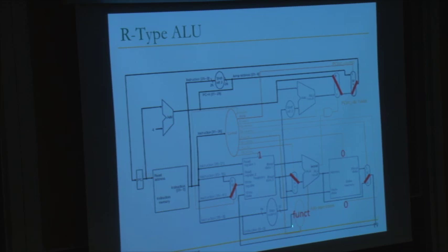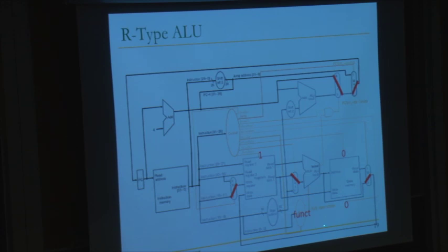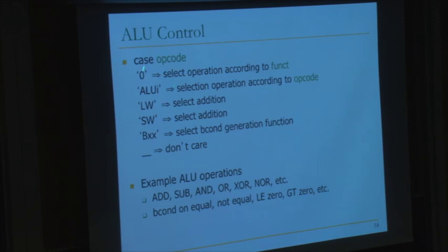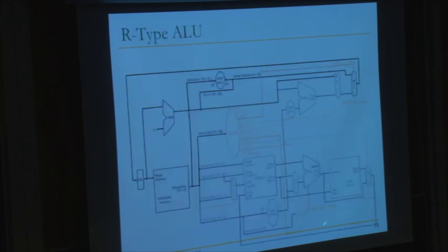And there should be some logic here that actually determines what the ALU should do, right? You're going to implement this logic. So control actually is not only this block, but also this block, right? Which includes the branch condition logic too. So if this is not a branch, you're going to select this function based on the opcode. That's actually, it's not only a branch, but based on this, you'll implement this logic. Okay? Well, you're not reading from memory or writing to memory, so you can set these to 0.